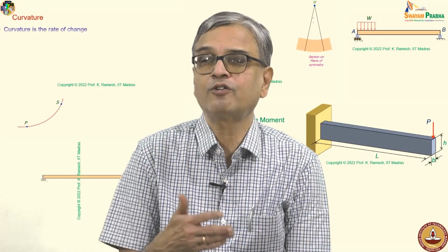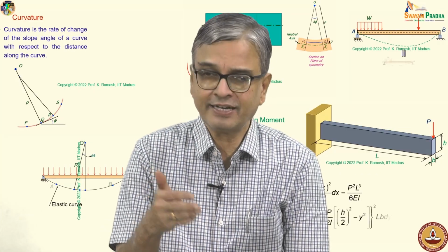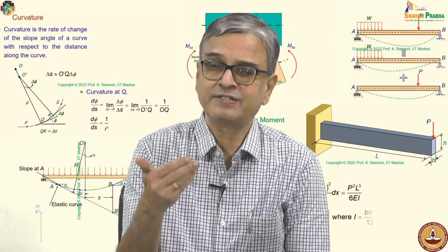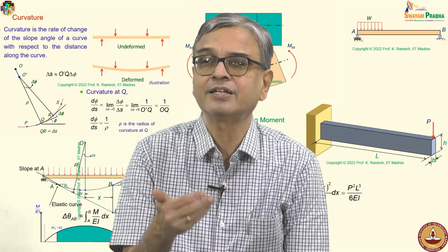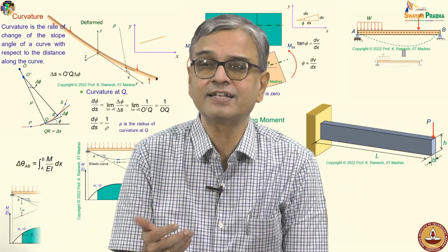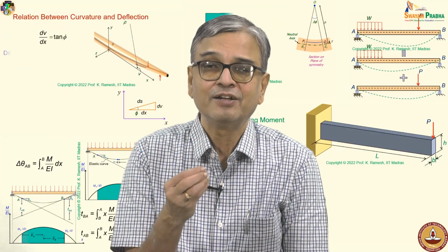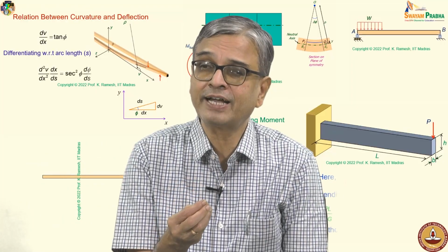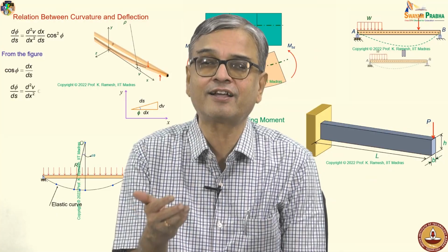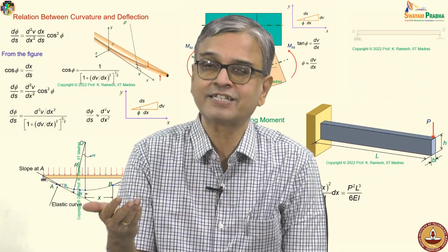So you have to find out, the name itself says moment area. Area is nothing but integration. Okay, that's why instead of doing a physical, mathematical integration, we do it in a graphical sense. And when I go in a graphical sense, only if I am in a position to find out the area, which becomes simpler, the bending moment diagram becomes simpler when I have concentrated load. When I have distributed load, I am going to have a second degree curve or third degree curve depending on what kind of load variation I have.